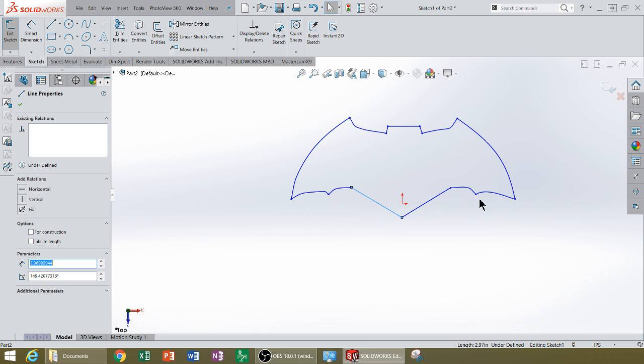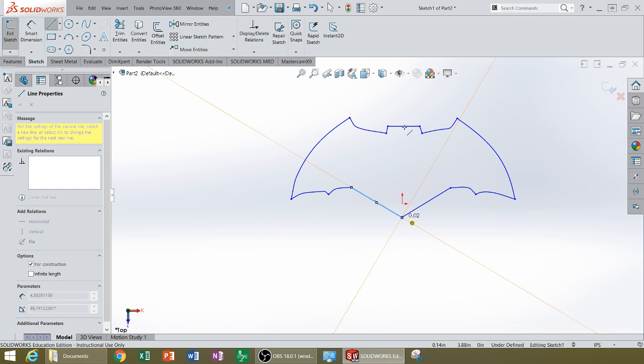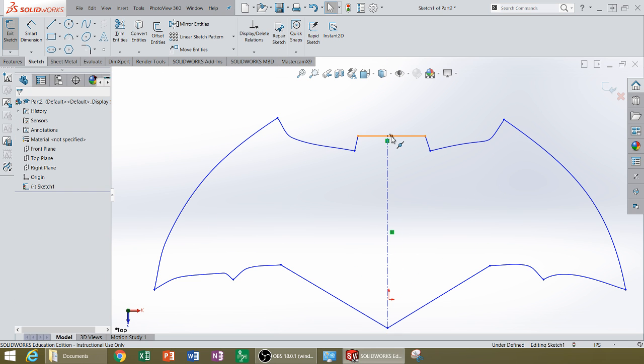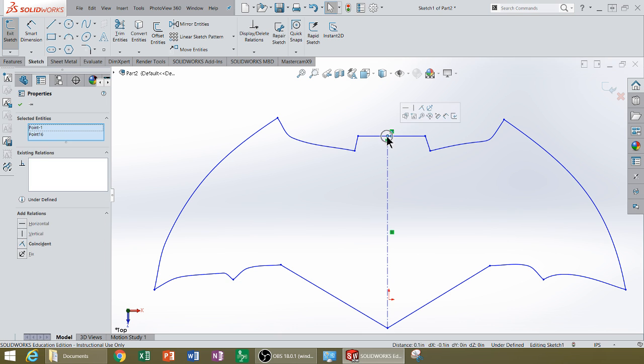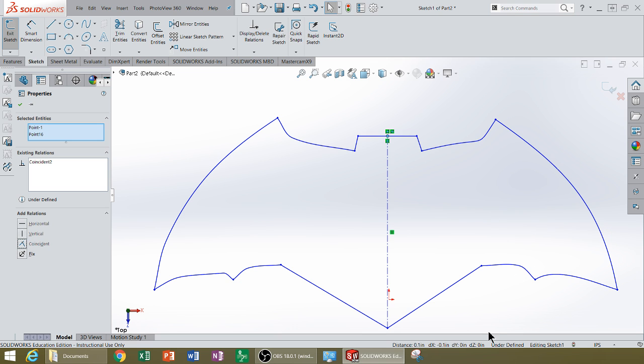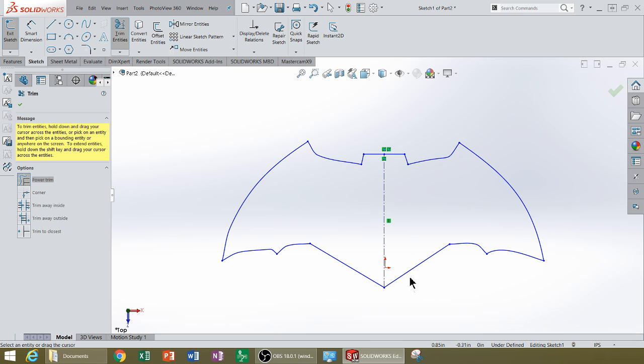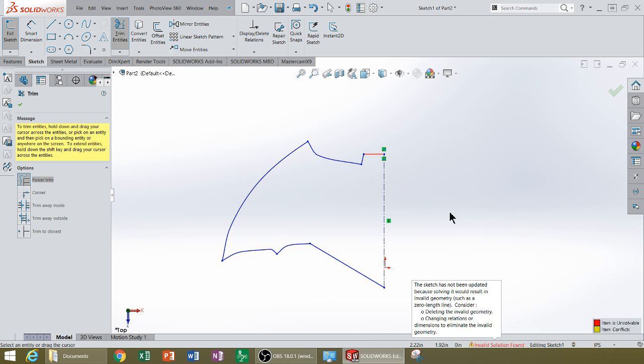If I really wanted to make this thing accurate, what I would do is mirror it. So I'm going to start that right now, and what I'm going to do is draw a line, a center line in fact, straight up. And I'm also going to choose the center point of this center line and make these two coincident. So now I'm close to symmetrical, but now what I'll do is trim away half of this image using my power trim tool.